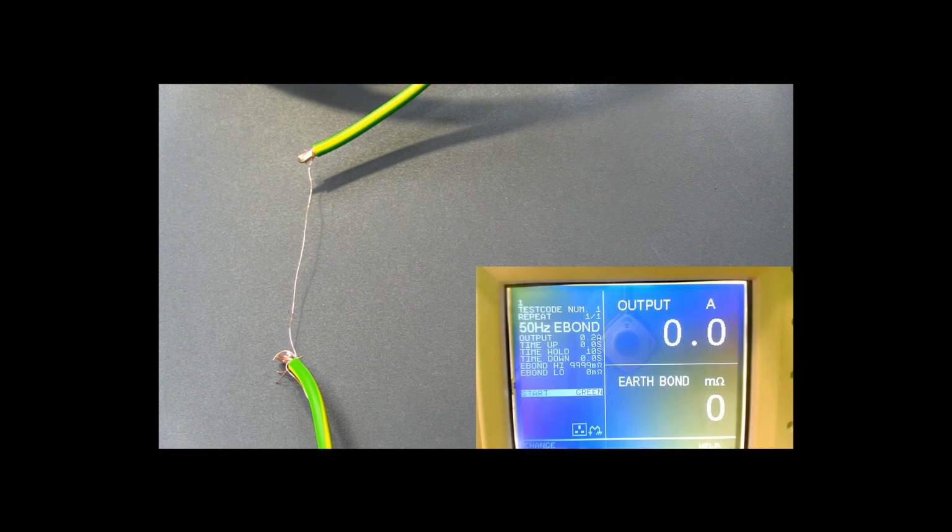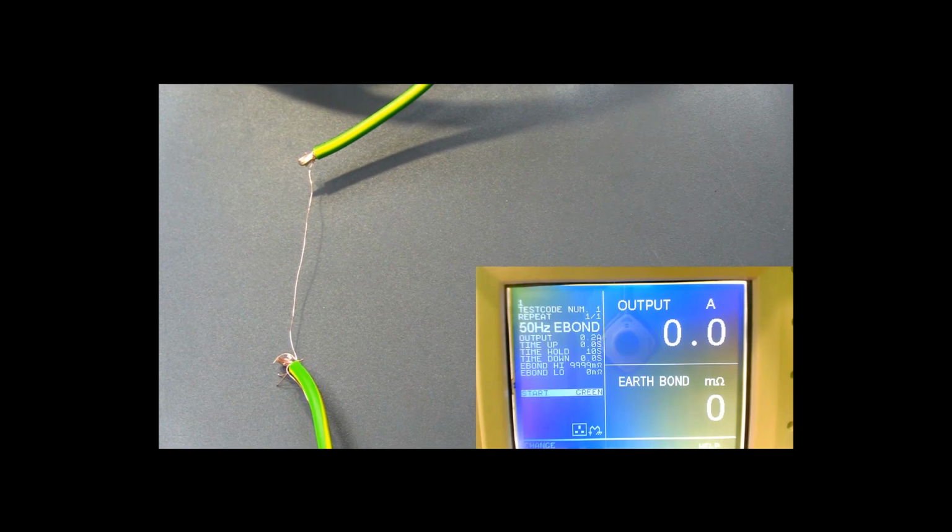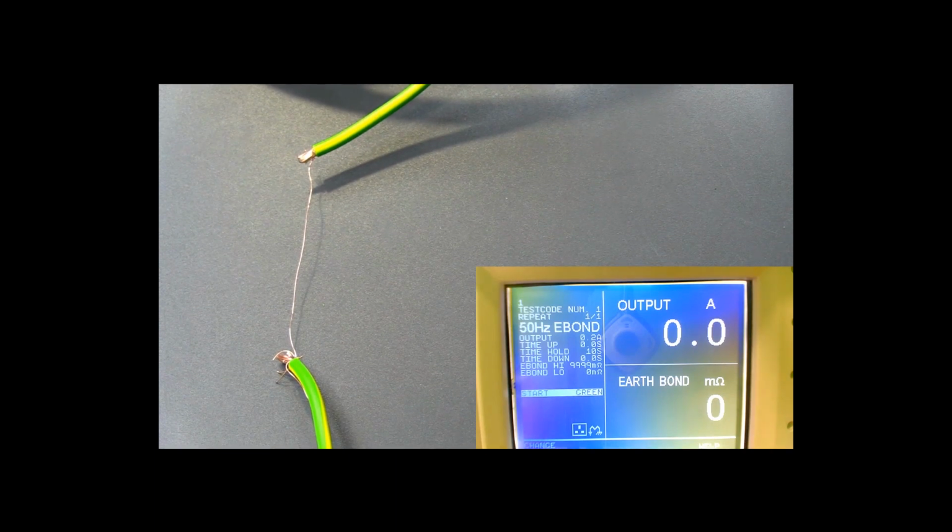Now, albeit this being the extreme of the kind of conditions that you could see, what we'll hope to see here is that whilst performing the test at 200 milliamps, current will flow freely across that last strand, won't have any effect, and effectively could carry that current all day long. What we'll then do is we'll up the current to 20 amps, so we'll effectively multiply the current by 100 times for a typical bond current, if you like, and we'll see what the effect of that has on the cable. So let's go ahead and start the test away at 200 milliamps.